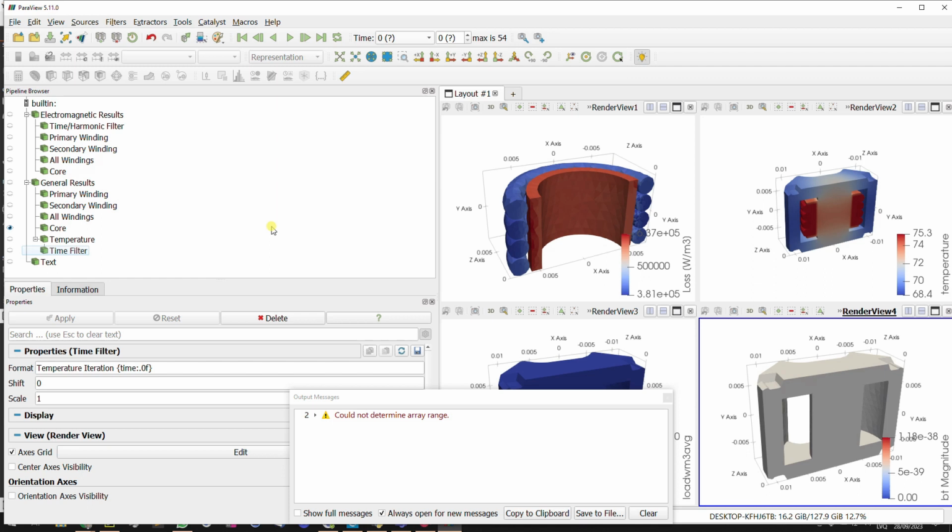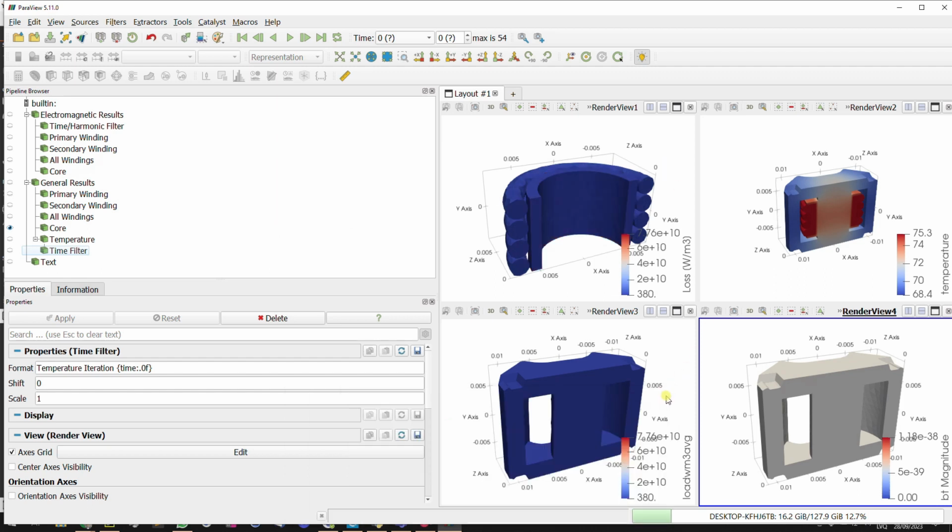Further, of course, there are some limits if you go into very high frequencies. I think the solver is not accounting for capacitive effects and for electrical field and magnetic field coupling. So typically it would be called a low frequency solver.